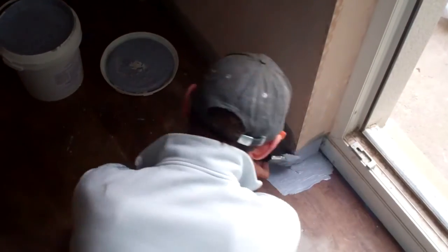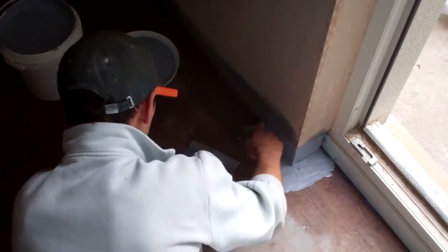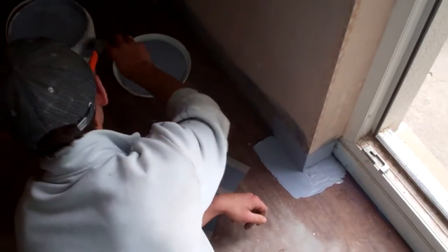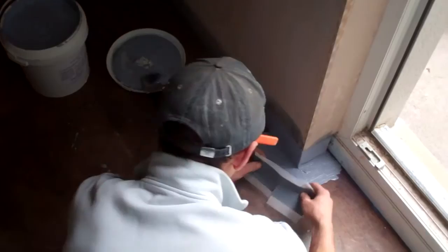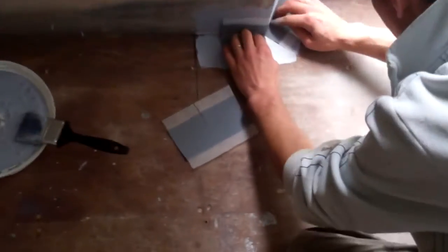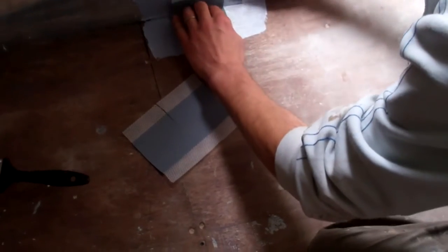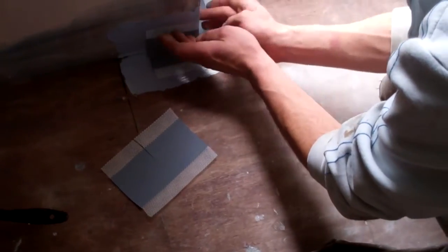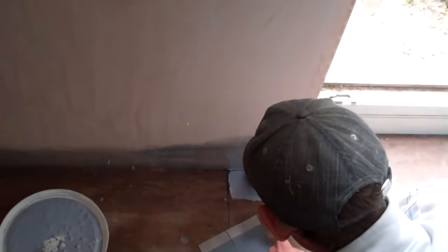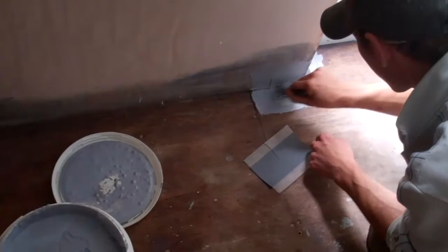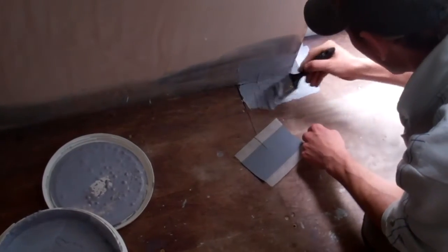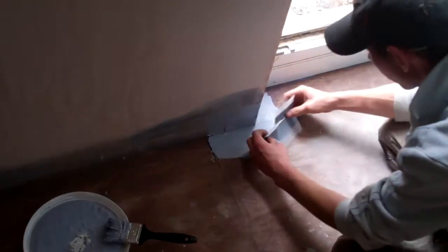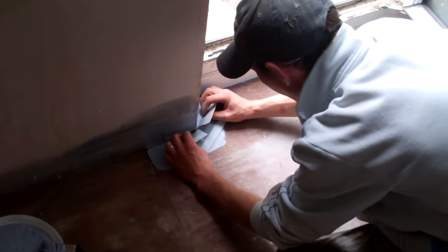Start off by applying the Aquaproof compound in the same manner as for the preformed corners. Next take a 200mm strip of Aquaproof tape, cut it centrally halfway through the width of the tape. This piece can now be turned around the corner and bedded into the compound. You can see that the cut in the tape splays out to form a square on the floor where there is currently no tape. We can now apply another coat of Aquaproof compound over the entire corner area.